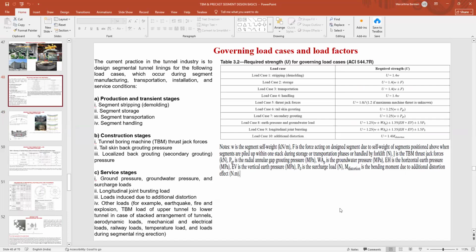First of all, this 40-50 cover, you cannot get uniform along all parts of your reinforcement. Because the reinforcements are not straight, it is a curved reinforcement. You have the bolt pocket, you have the grout socket. So at several places, you will get several covers. And the second thing is that if your exposure class is very high and you have already started production of the reinforcement, then either you make it epoxy coated or you cover it with a plastic sheet.